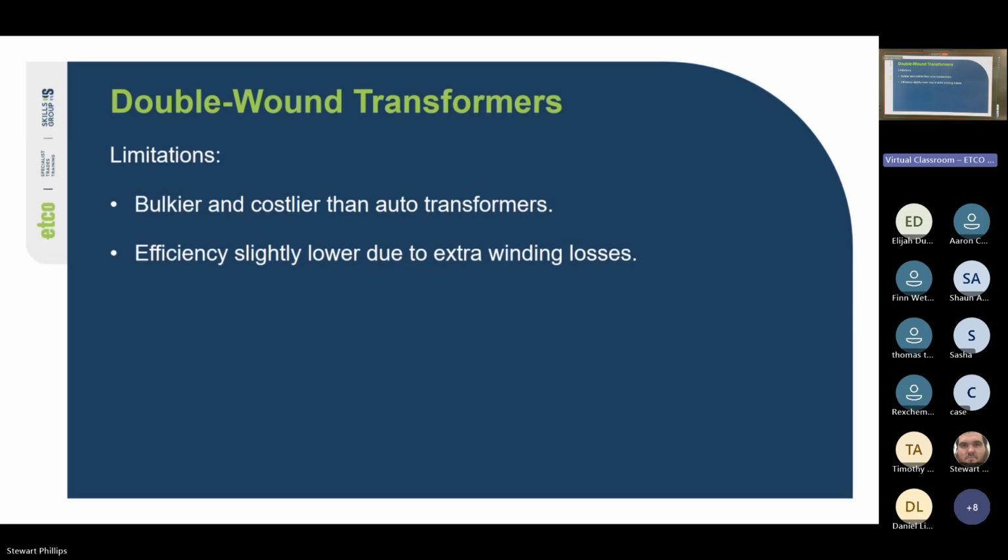Yeah, you definitely want to keep the 220 to 110 completely separate. Sometimes we do use them a lot and we forget about it. So if any of you guys have done garden lighting, you use a transformer. Yeah, drivers, 230 to 24 volts, your standard drivers. There's a double wound inside those.